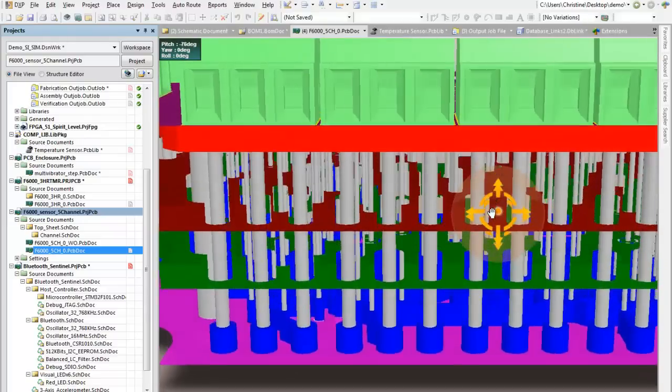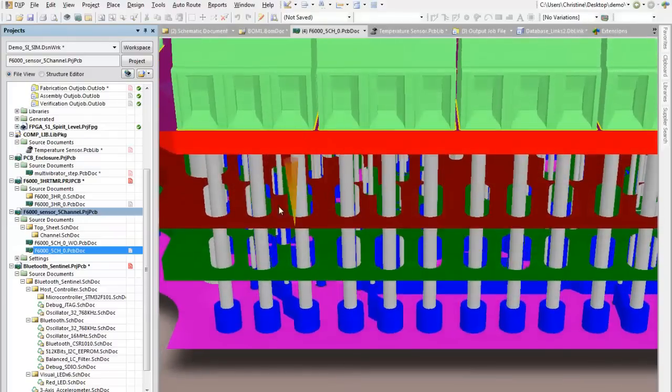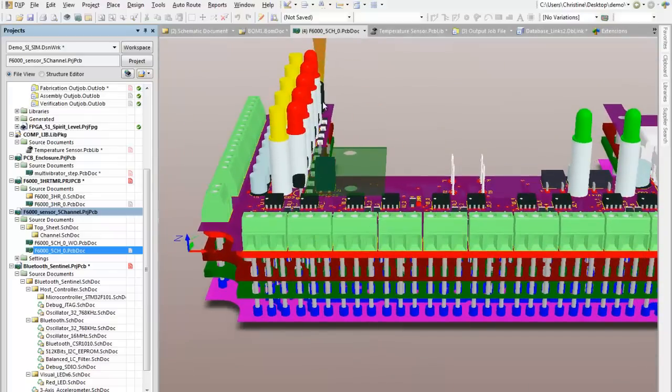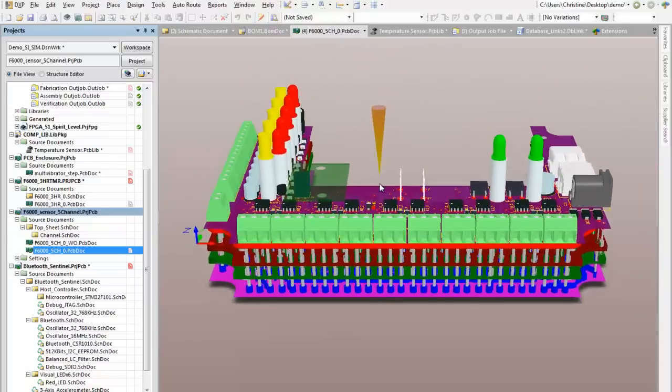Not only that, I can also look at the clearances. Make sure that they aren't impacting any portion of those areas that are considered the through holes for that particular pin. And imagine these heights, they're pretty large here as far as the heights for those components. If this were going in an enclosure, I would want to know that immediately. And this is one way of identifying if I were to place an enclosure in the PCB editor, just as we had seen previously, it would flag me with any of those constraints that might be in violation.